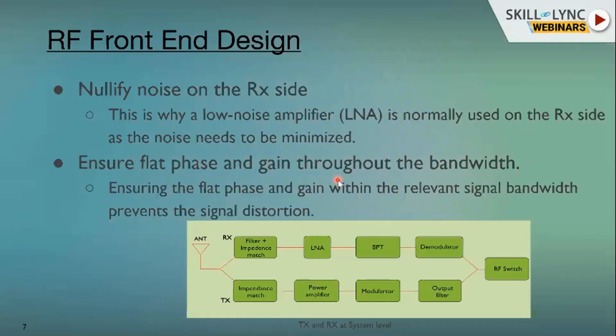So if you look at it, it may not work from 800 megahertz till 7 gigahertz, but it has particular bands. Like GSM works at 700 to 910 or maybe 960, based on the location or geographical position. At the same time, Bluetooth works at 2.4 to 2.5, and your Wi-Fi works at 5 to 7. Again, it depends on where you want to fit it in your set.